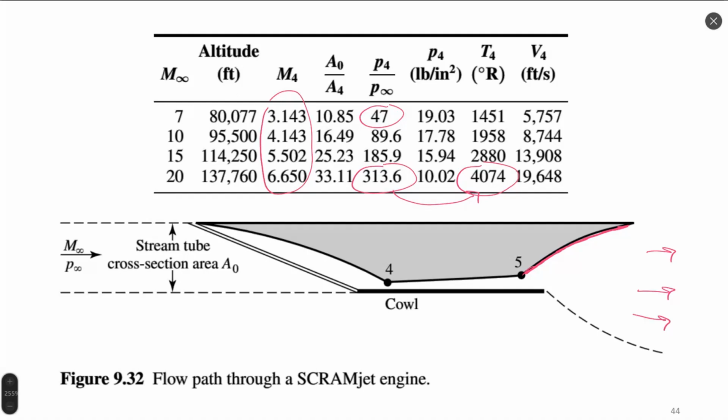And such expansion can create a process called thermal block of flow. Flow expands in all directions, and if we heat too much, such flow can just stop because expansion is very big. So to compensate expansion due to chemical source and heating of flow, we must increase area of the flow duct. So in such case, area 5 is bigger just to avoid thermal block of flow.